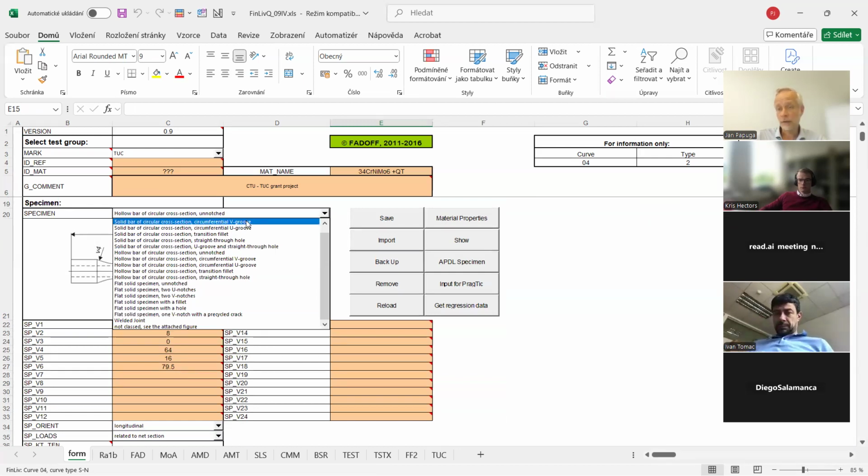Because if you check that in reality, if this is not a very special case of, for example, contact fatigue or whatever else, or very industrial cases, the number of configurations is very low. This is the reason why we believed that we can proceed to APDL with generating automatically, based on just geometrical configuration, finite element models, which could be quickly prepared and processed.